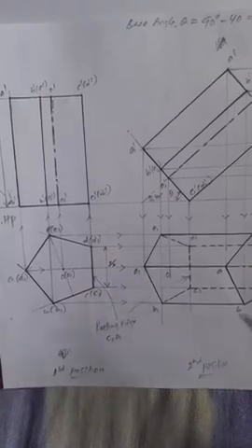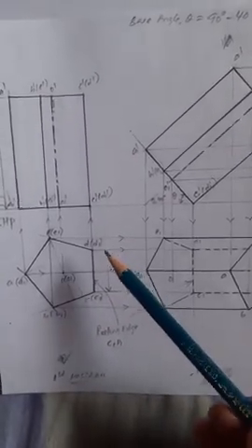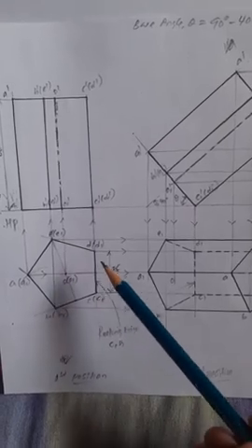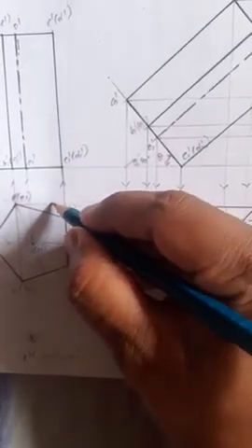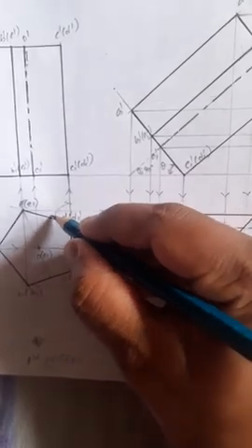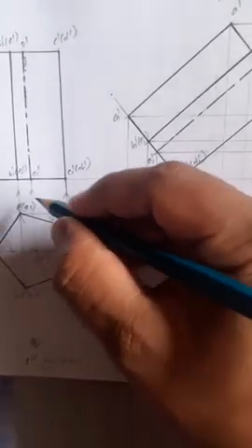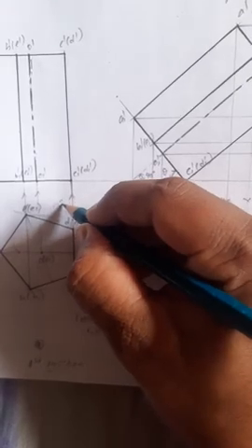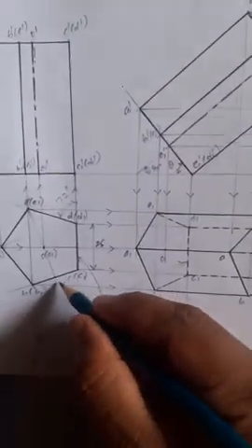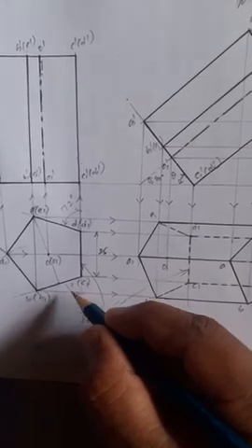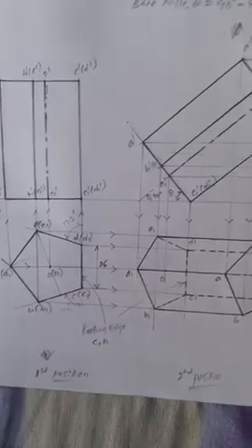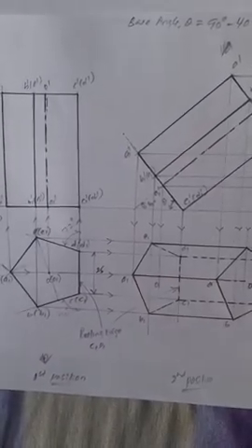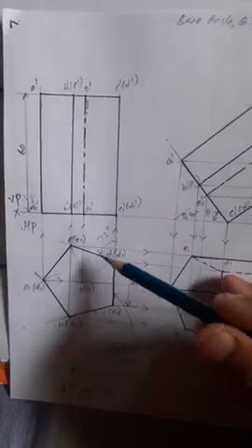Now you know how to construct the regular pentagon, right? How do you construct it? First draw a vertical line. On the vertical line, we measure 25 mm. As you know, the exterior angle of the pentagon is 360 divided by the number of sides, 5, so we get 72 degrees. Draw a 72 degree line on both sides, at the corner of the line.